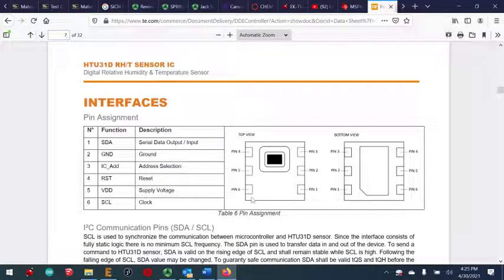One thing I noticed is that this is kind of upside down. Usually you see pin 1 up here, and when I design the footprint in EAGLE, I'm going to set it up that way. So I'm going to want this piece that you see when you look at this on the bottom instead of on the top. You'll notice that there's also this thermal pad on the bottom, and I believe that's probably grounded, but it doesn't tell you that over here. We're not going to worry too much about that, but I'm going to make a little change when we set it up.